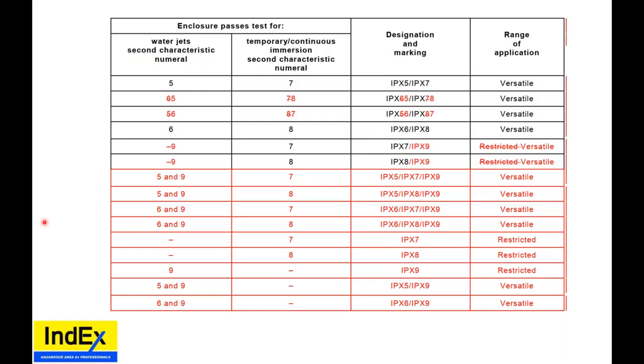As per equipment minimum, IP54 is deemed enough, but they can still test to IP66, or is it a manufacturer requirement? Once again, IP54 is a 10-minute test, while IP66 is only a 1-minute test. The manufacturer can ask for greater testing, greater periods of time, greater pressure, greater temperature. Some manufacturers only tested their equipment for 3 minutes at IP66, and it has failed within Australia. Because when a cyclone comes through with 300-kilometer-an-hour driven water, it's going to fail, which then negates the EX protection technique: water inside, arcing, sparking, potential source of ignition.